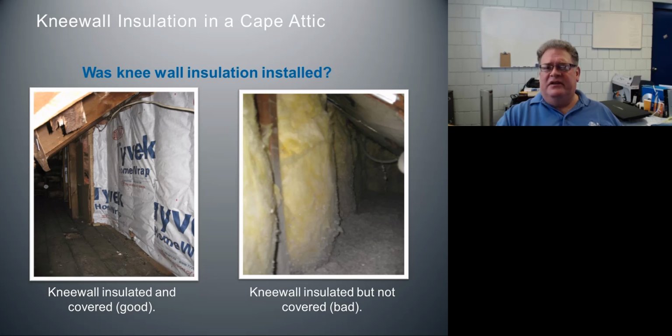We have air that's trying to move this direction and over the top of those batts up a slant wall to the top attic, or to a vent system that would be higher up in the rafter system. But what's happening is we have cool air coming in low on this and then rising, and that air is going to start convecting as well. In other words, it's going to start a convective loop and driving heat right into that insulation.